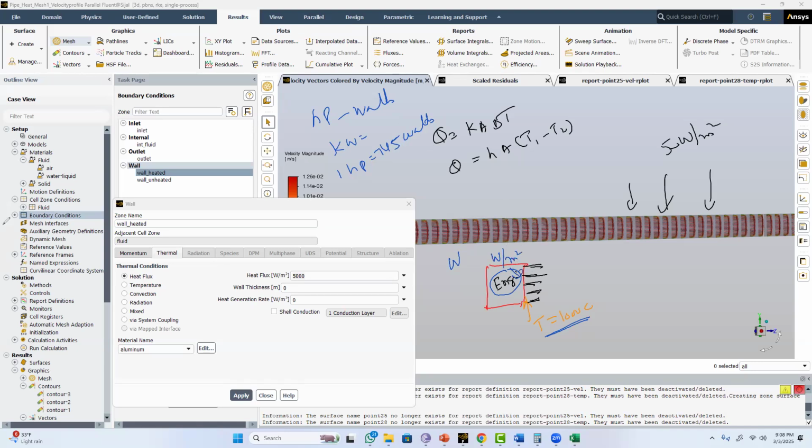This is like cooking your food on the stove. You are providing heat on the bottom side, and that heat is at a constant rate, Q is at a constant rate. What is going to happen is that if you cannot dissipate the heat from the top side through conduction or convection, mostly natural convection, to the surrounding, the temperature will increase inside.